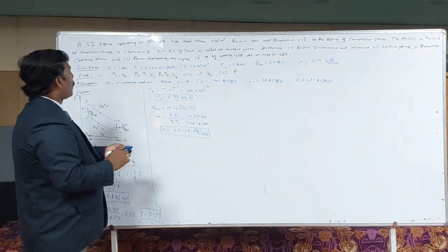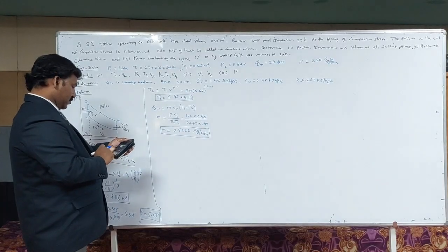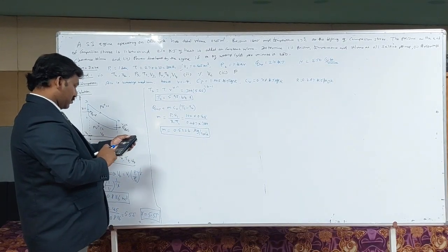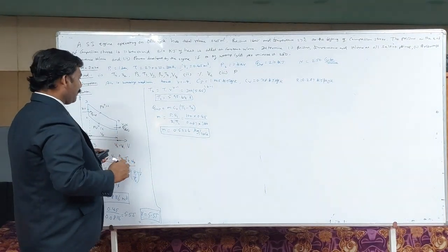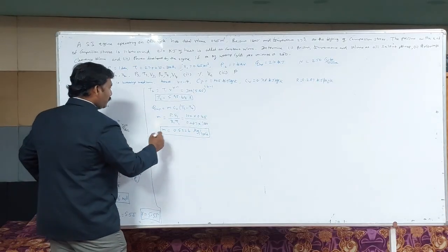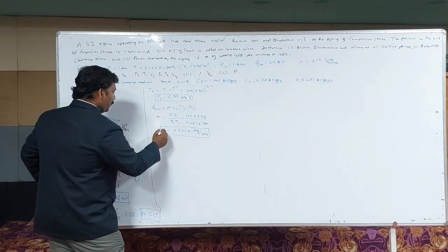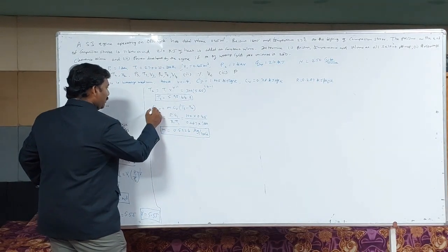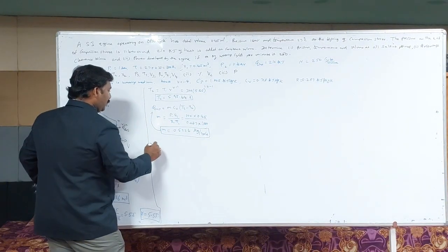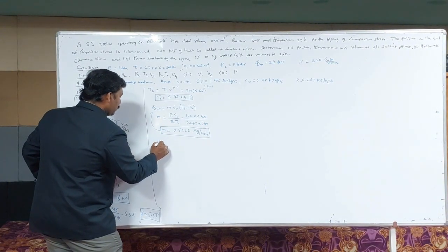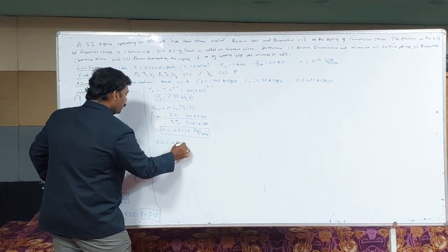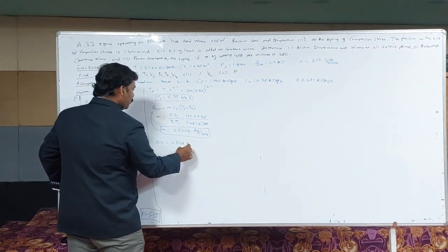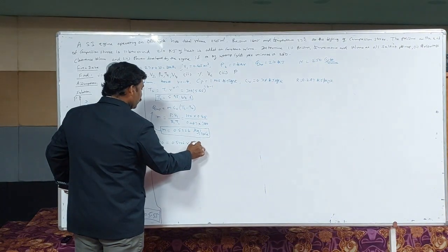All right. So 0.5226 kilogram per cycle. And we have to now find out T3, substituting the mass in the heat supplied equation. You get 210 kilojoule is equal to 0.5226 kilogram per cycle into Cv value 0.718.